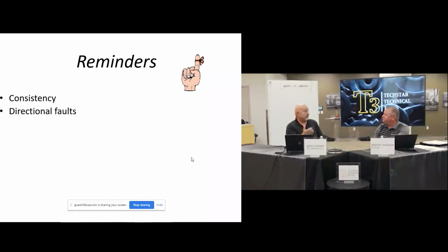Sure, exactly. Let's say you want to mount a probe on your gearbox and a cooling fan. Normally you mount one on the input side, horizontal, and it's based off people's budgets. But you can get an accelerometer with armor jacket cable, 20 feet long, for about $175, $200. So if you wanted to put 5 in there, you could.